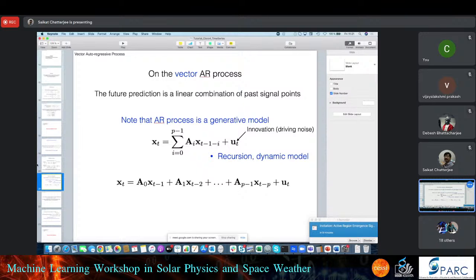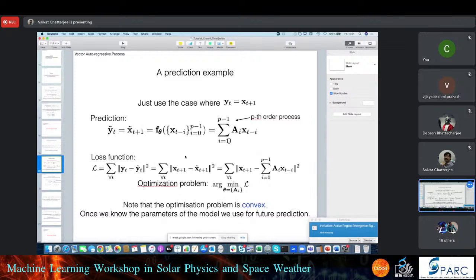Now, if you see this model, what basically I treated? I treated x t plus 1, this is y t, and this is my error signal. This y t tilde is the prediction signal. The prediction signal means that using the past samples, what you are able to predict, and the error is the part which you could not predict, right? It's clear that the error is the part which you could not predict. y t tilde is the part which you could predict, right?